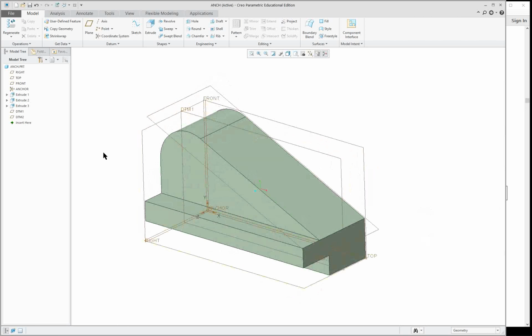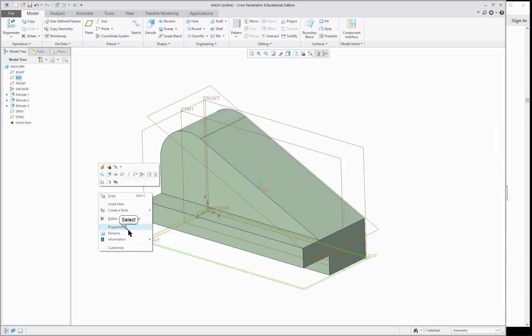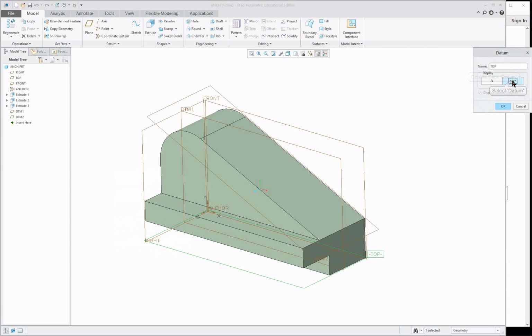And since we did the datum plane, we might as well set the datum planes. So I'm going to click on the bottom here, which would be datum plane A, using geometric tolerancing. And A, and then enter. You don't have to type in a capital. It'll make it a capital. And I'm going to put the datum tag on there. And here's datum A. That's on the bottom.